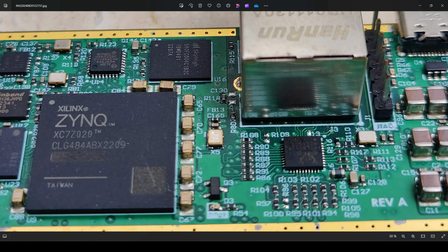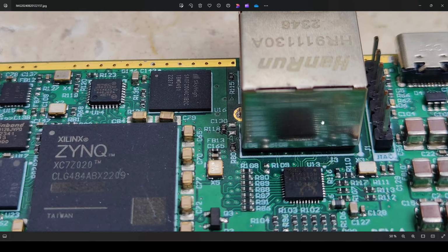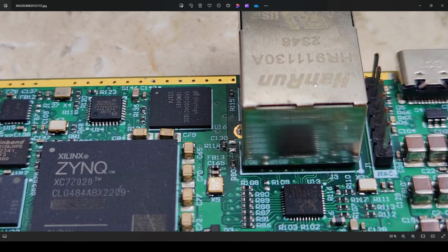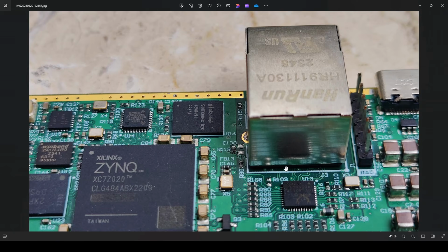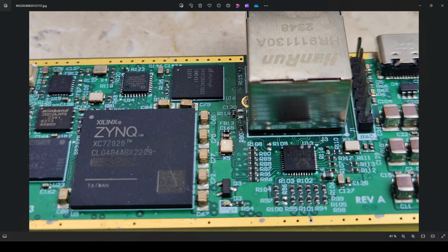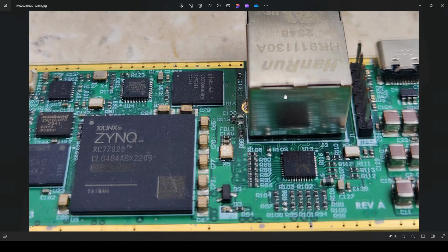And from that physical layer, we then route with 4 differential pairs to and from this RJ45 connector with integrated magnetics. The reason I chose an RJ45 connector with integrated magnetics, MagJack for short, is that it makes the routing far simpler, and it saves onboard real estate, because rather than needing external magnetics between the physical layer and this RJ45 connector, the magnetics are integrated into this connector.